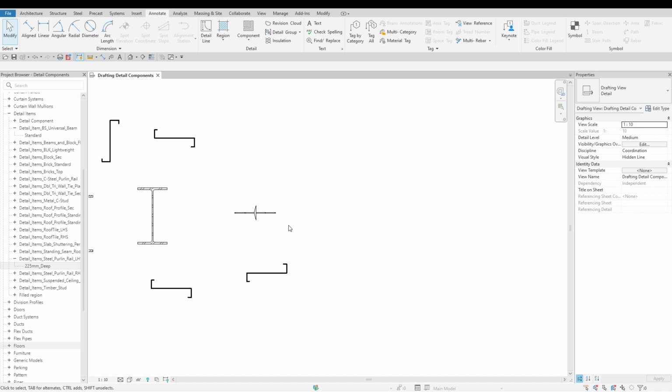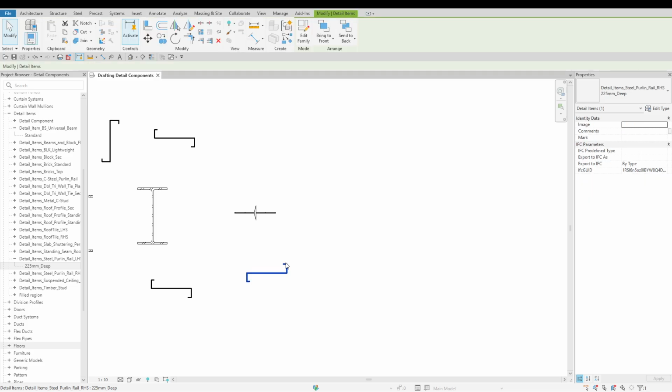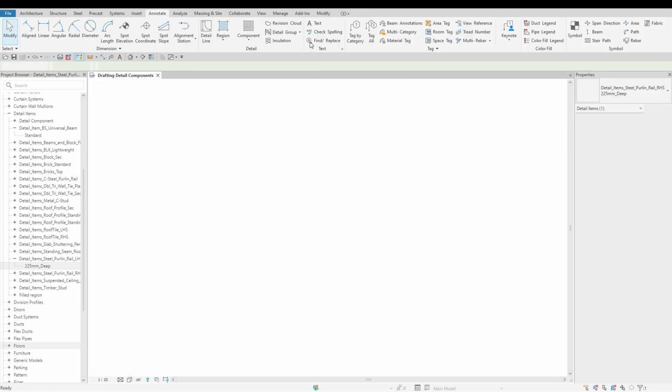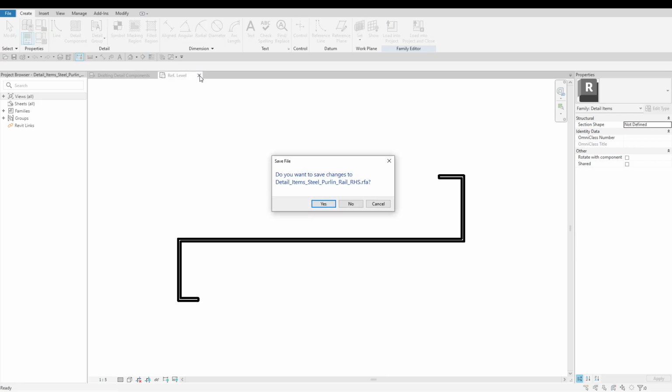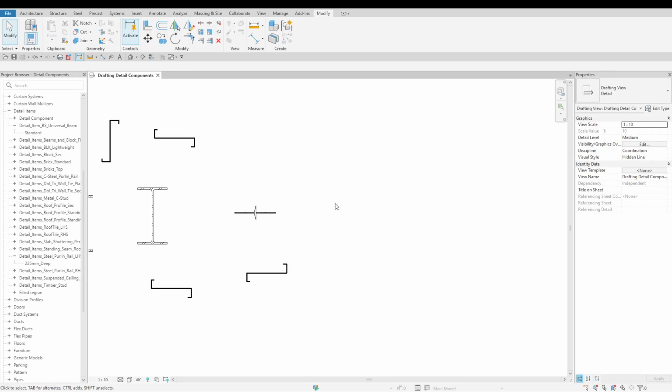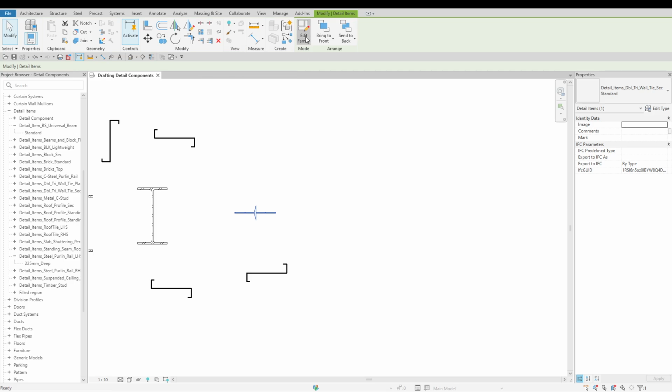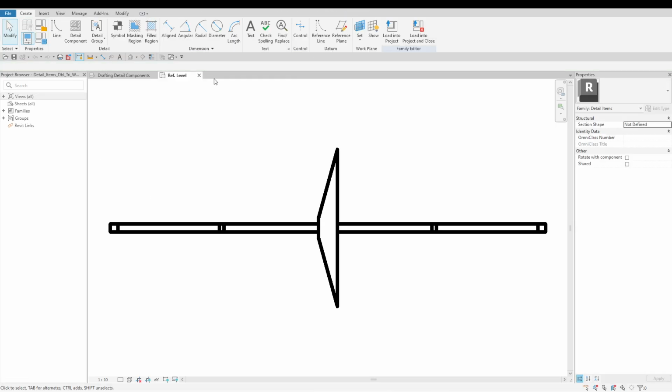While the process may vary slightly depending on your design intent, these core steps remain widely applicable across various detail types. To create a custom detail component, you can either modify an existing family or start from scratch. To modify an existing family, click on it and select Edit Family. Here are two key benefits. Time efficiency: modifying an existing family saves time by building on pre-existing geometry and parameters. Consistency: it ensures your custom details align with the project standards, maintaining compatibility with other components.